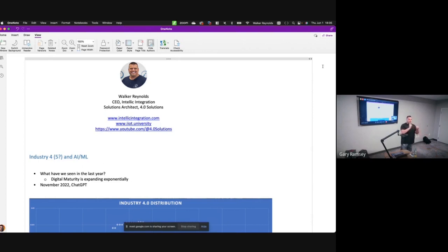We would love to know what they're printing, on what printing press are they printing on, how fast are they printing, what's the web tension, what's the relative humidity, and what's the temperature in the facility when they're using the ink. So that when we get a quality return, we could look at the digital data we've collected while they were running our ink on their printing press.